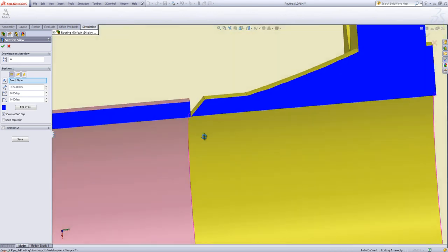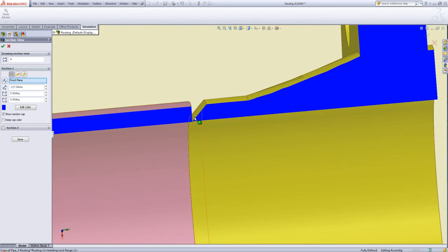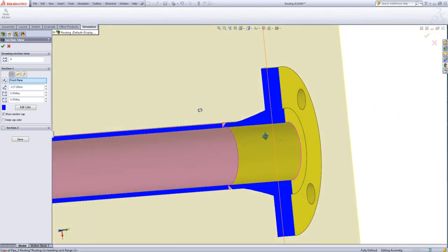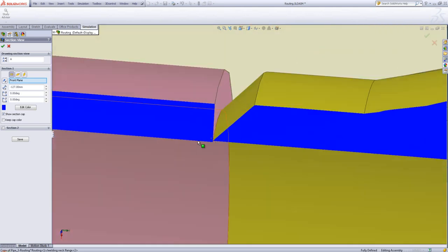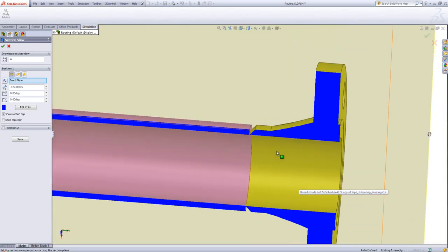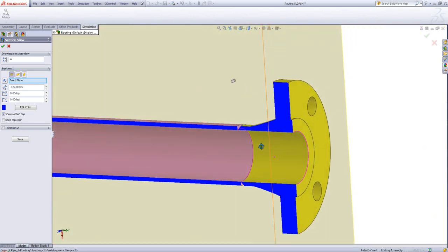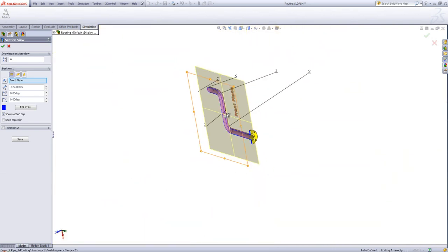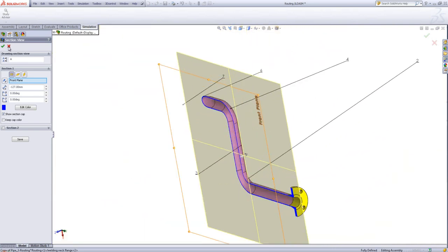The key area of interest is this region here. You'll see where we've got the flange attached to the pipe, we have just got this cutout here, which would be where the weld bead would go. So we're going to have to deal with that pretty specially, because we've just got essentially an edge-to-edge contact there. We're not too happy about the way that bond is being executed. So we'll have to be very careful when we come to that in the analysis.